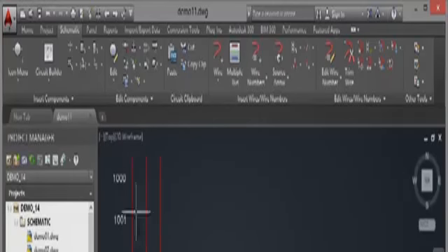We're staying in the Demo 11 drawing in the Demo 14 project. The Demo 11 drawing is the one we used in the previous video to insert our three-phase ladder and our three-phase multiple bus wiring. Now you'll notice I've updated the wire type to make it red. That's just using a new layer and creating a new wire type for this particular drawing. We can add three-phase symbols to our AutoCAD electrical drawing as well. And the nice thing is they're all parametrically driven.